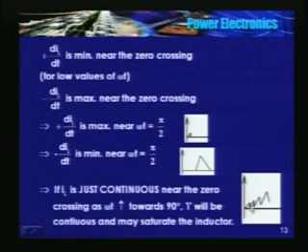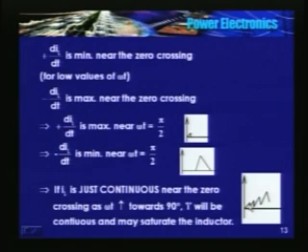Okay, I will repeat. See, I have a very small value of current and it touches 0 here because it decays very fast. When I close the switch for the second time, since VO1 has increased, this peak has increased, but then the rate of decay is slower compared to this period. So when I close the switch for the third time, there will be some current in the inductor. Okay, current will not become 0.